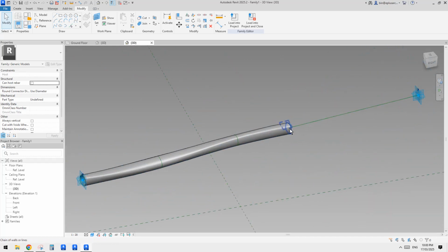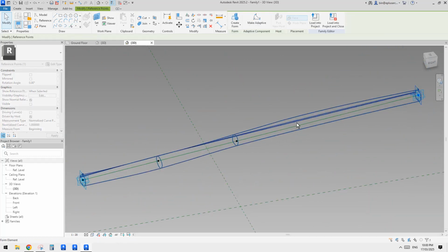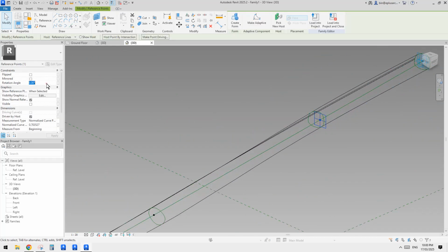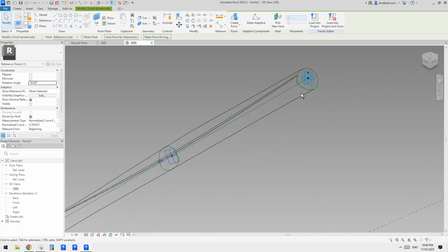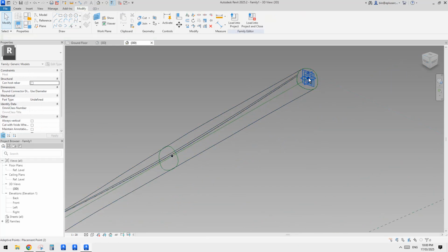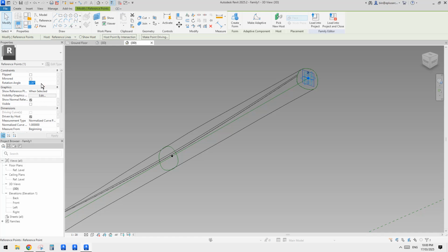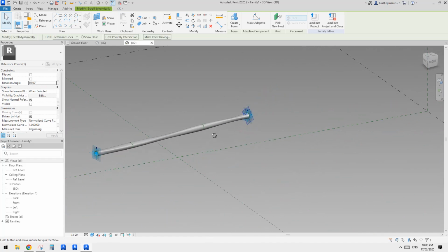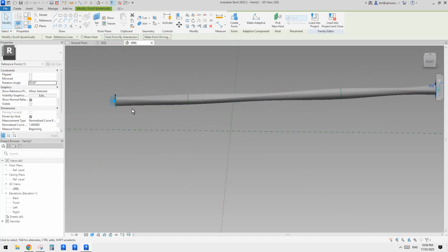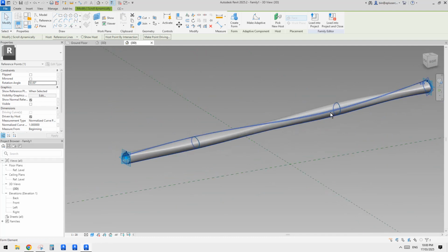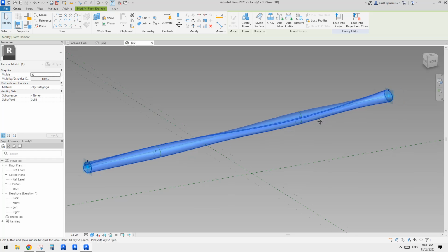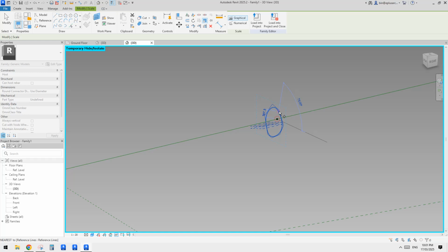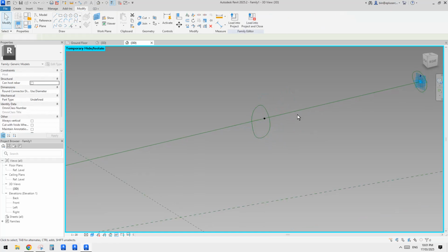So again, let's drag this to this end, drag this to this end, and then rotate this one, so negative 30 degrees for example, and this one, not this point, Tab to select, maybe 40, 50, right? Oh yeah, it's still okay. Maybe we can just increase some of the size, select it, RE for scale, so scale to change the size a little bit.